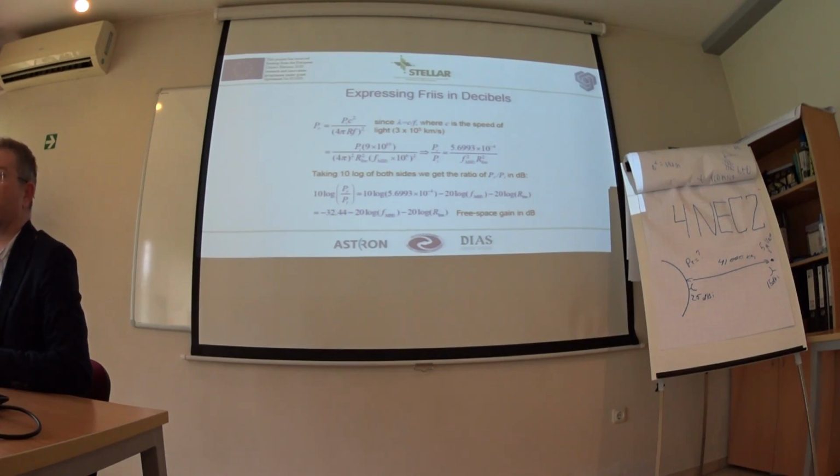First, the approach should be like that. First, you estimate what will be the power needed on the input of the receiver, based on the sensitivity, the required voltage, and the impedance of the input. Then you convert this power to dBm, decibels against 1 milliwatt, and then you add all the losses, and then you will receive the power needed to be transmitted.